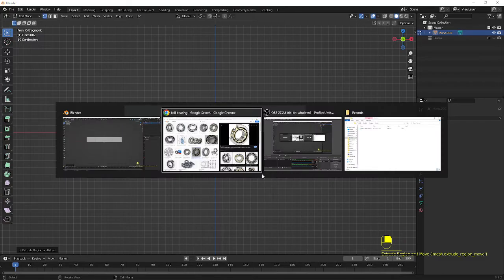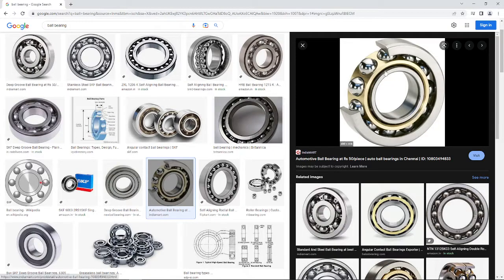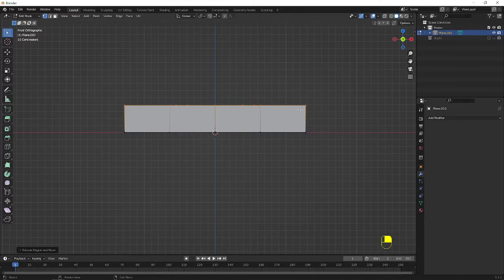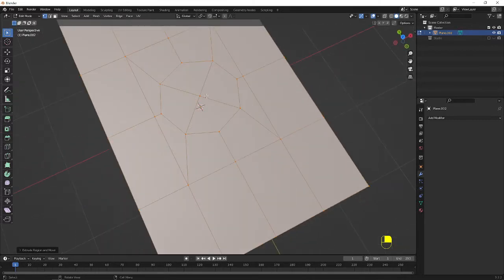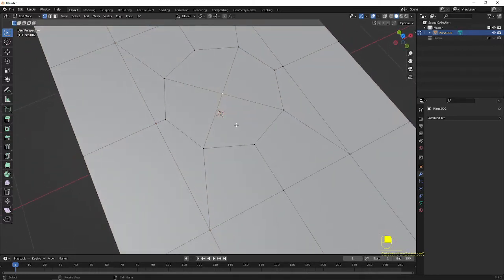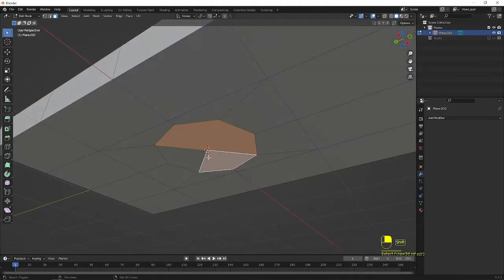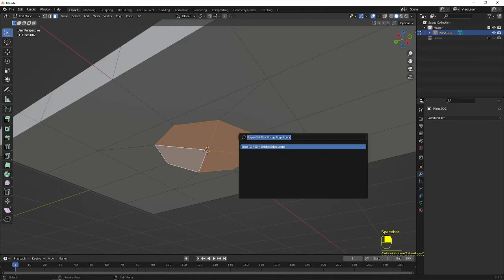much. So now I am just concentrating on that golden plated ring. So this design, then inner and then outer. So now I have selected this one. Now select the face here and select the face here. Press spacebar and search for the bridge edge loops and press enter.